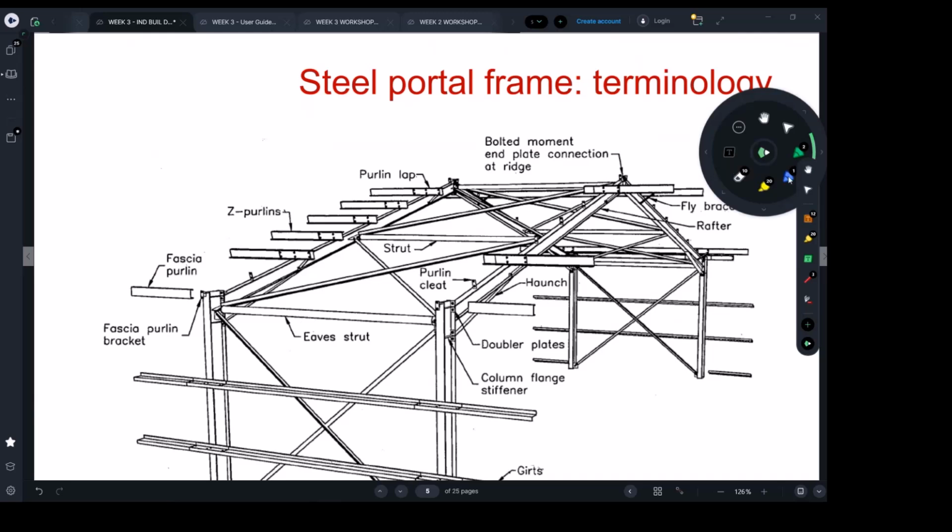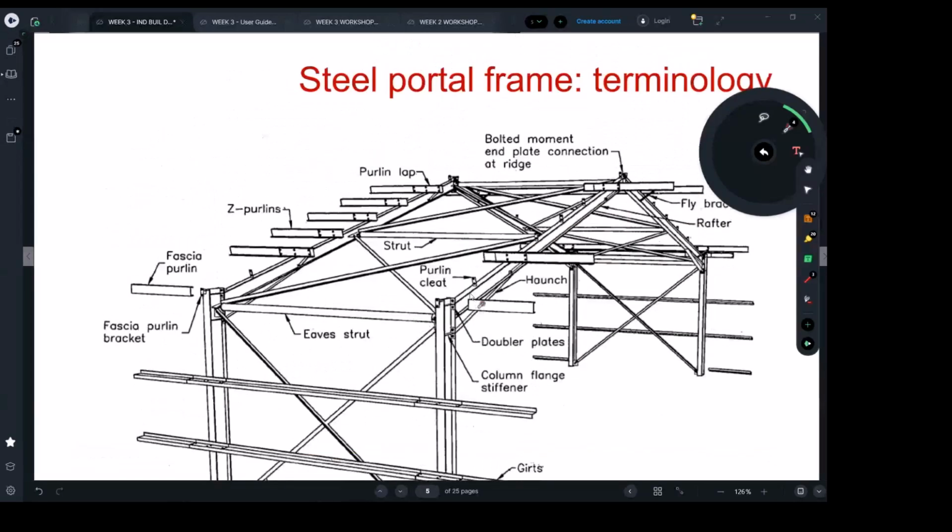Just let me clarify something because people may be confused about it. Someone will tell me that in this part we don't have purlins. It's not meant to stop. It's just for this image. They stopped them to clarify how the bracing works. So don't expect purlins to stop here. They should continue above the roof, but they just stopped them here in this diagram to let you see the roof bracing.